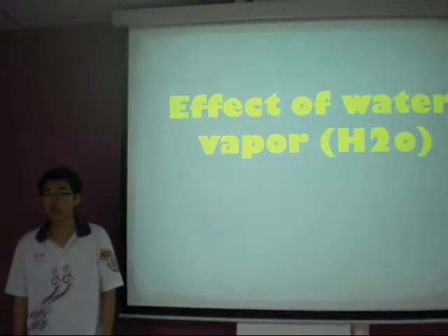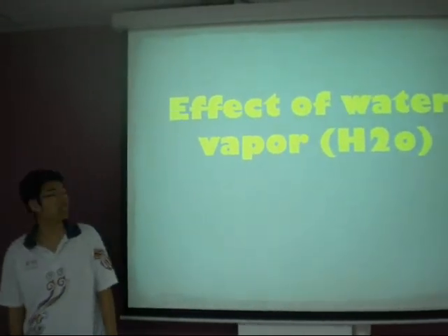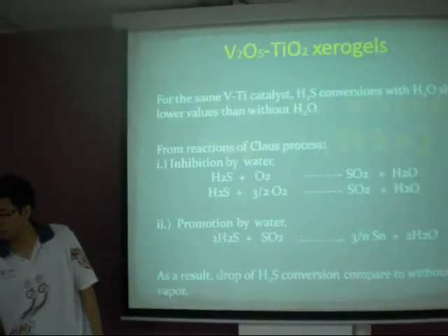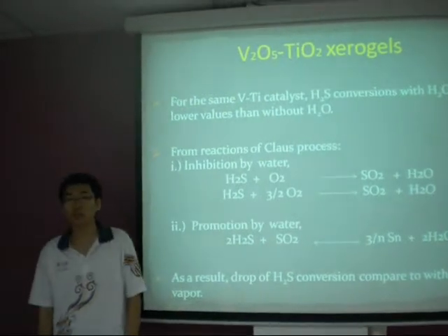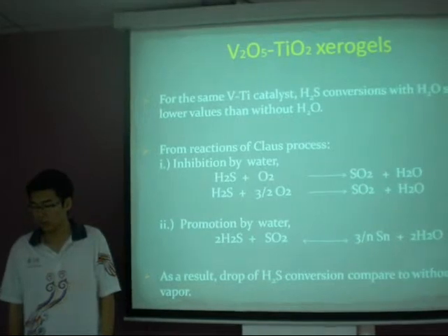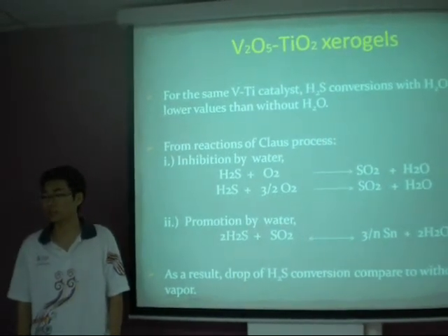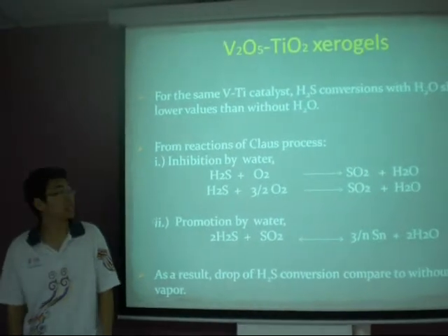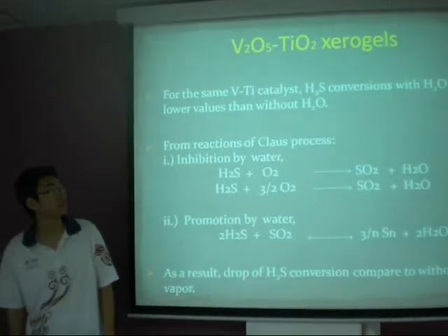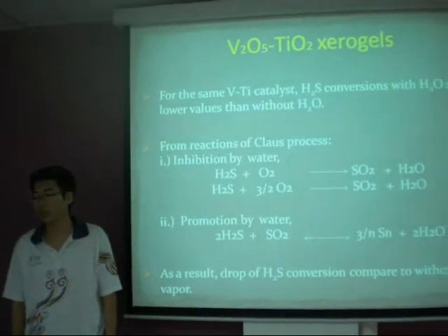Thank you. First of all, we will investigate the effects of water vapor in selective oxidation of H2S. Generally, the presence of water will lower the conversion of H2S. For instance, a vanadium titanium catalyst supported on titanium oxide aerogel was studied, and it was shown that the conversion of hydrogen sulfide was lower in the presence of water.